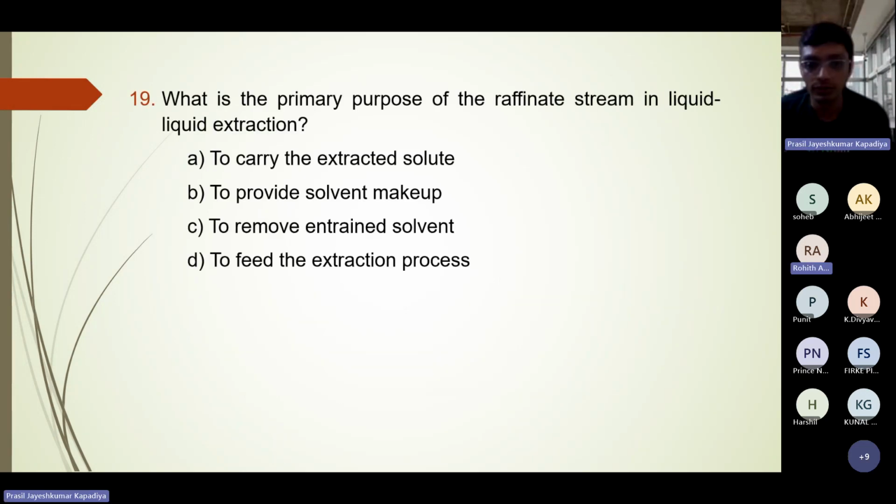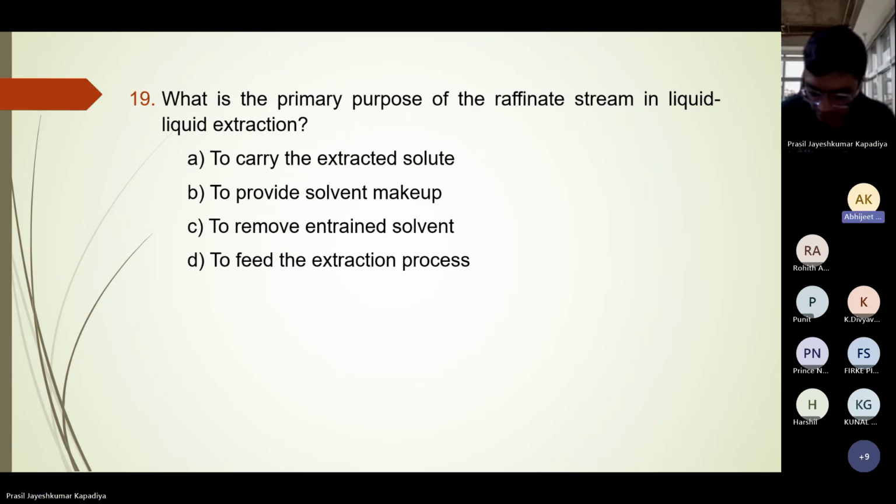We can also increase the diameter, yes, but once our column is set, it is in a steady state. While designing, you can do it. I don't remember those calculations, but you estimate some diameter and take some percentage of that diameter. I don't remember those values. There is a chart. We have to calculate the flooding capacity parameter.